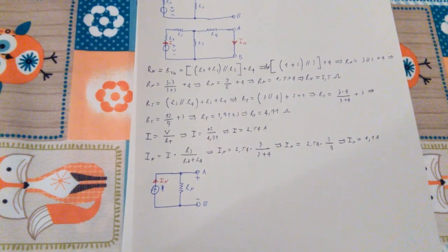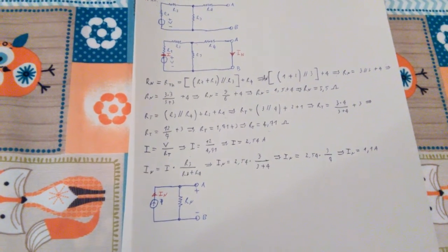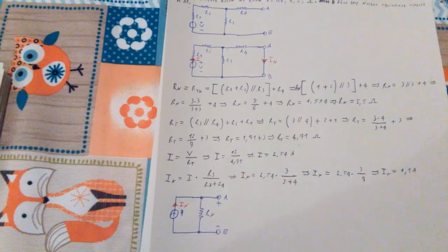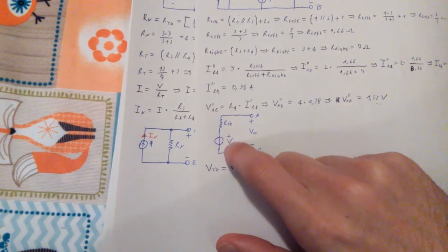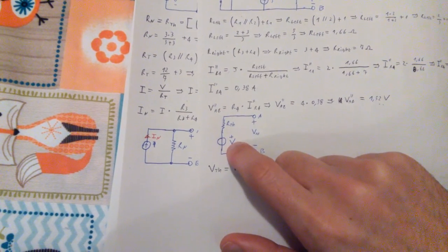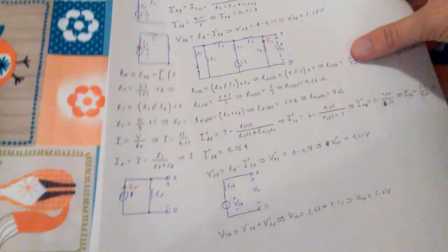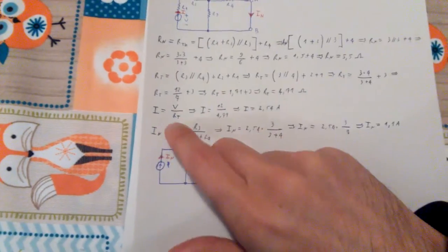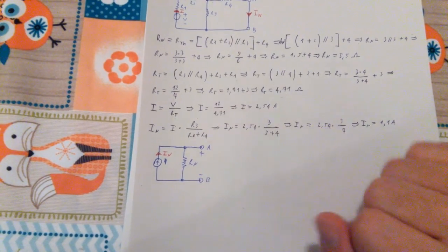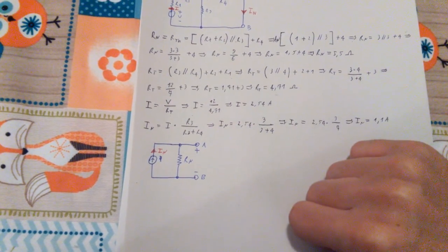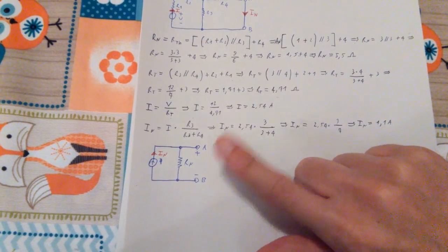So now I'm pretty sure you can see why it's called the dual of the Thevenin equivalent circuit, which is we did exactly the same thing for Thevenin, but we had the voltage generator, while in Norton we just had the current generator. So they're pretty much the same. Both are equivalent circuits, which we can find and calculate. And just Thevenin is with the voltage and Norton is with the current.